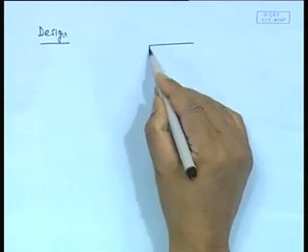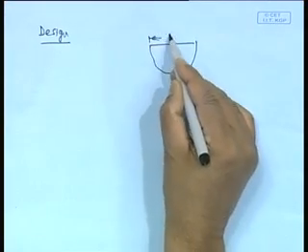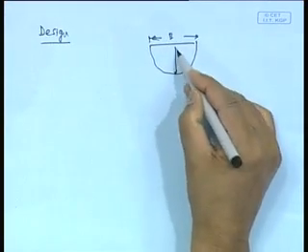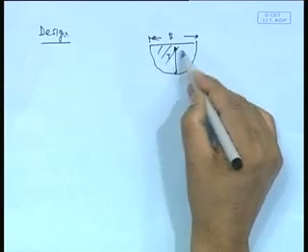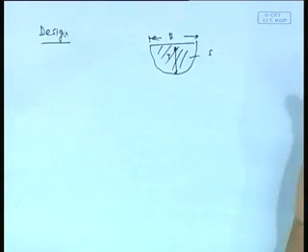One of the reasons is because for computing Seakeeping in the initial stages, you really don't need the lines plan or the hull geometry so accurately. All you actually require is an approximate shape. For example, if I knew the section shapes purely by means of local breadth, local draft and section area, I can actually determine sectional added mass, etc.